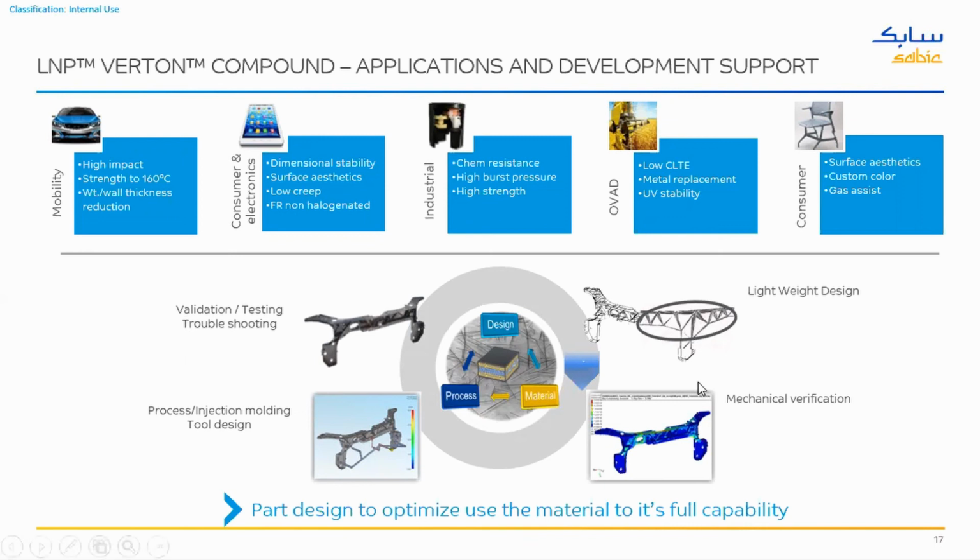And with that, long glass fibers are surely an opportunity for a wider application space across segments. In SABIC, we are focusing on a lot more applications. Mobility is surely one of the key areas where light weighting is very important, but there are also many demanding requirements such as impact, vibrations, and high temperature requirements. There the long glass fiber really makes a good fit in such applications for metal replacement.